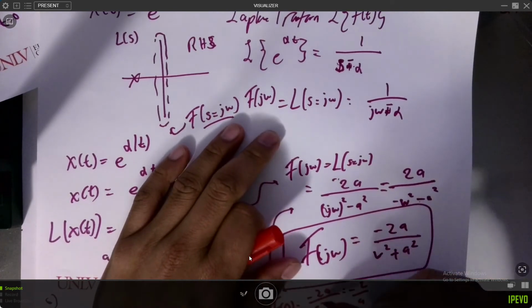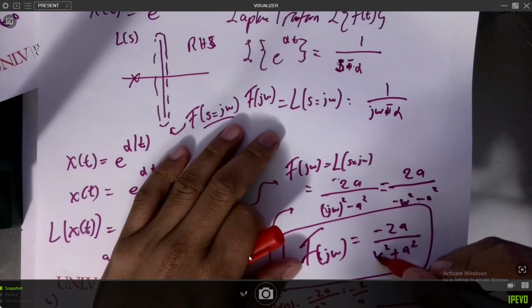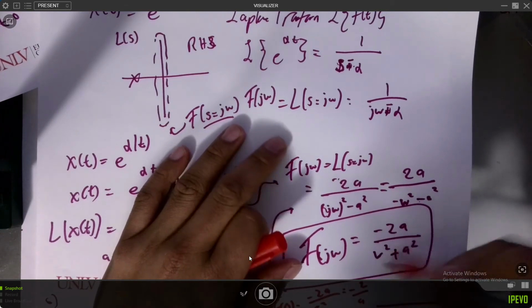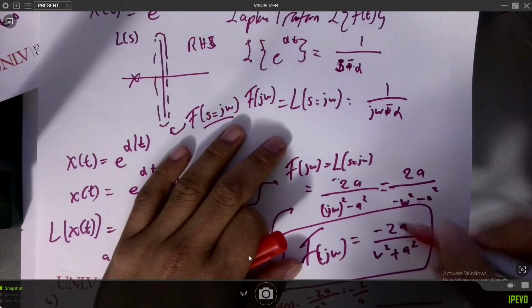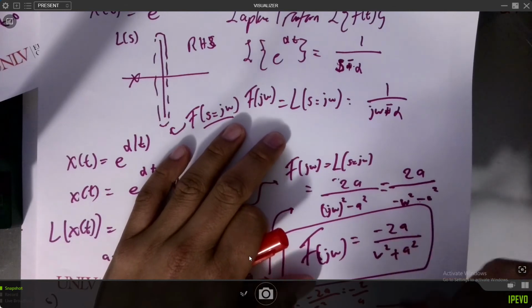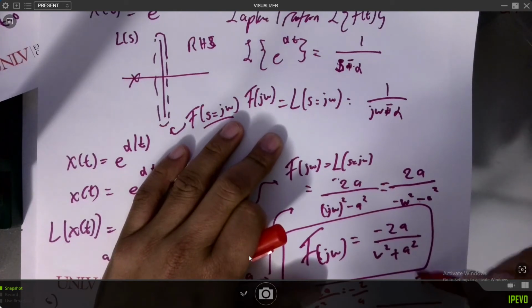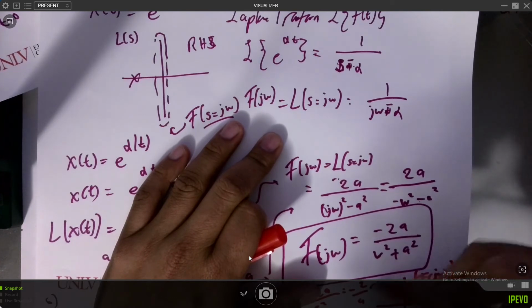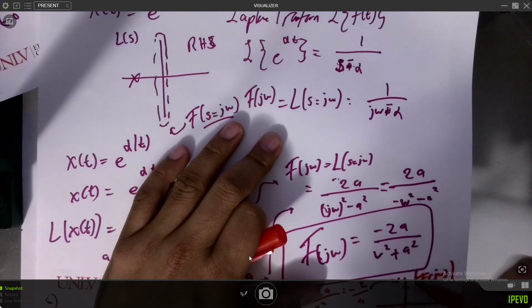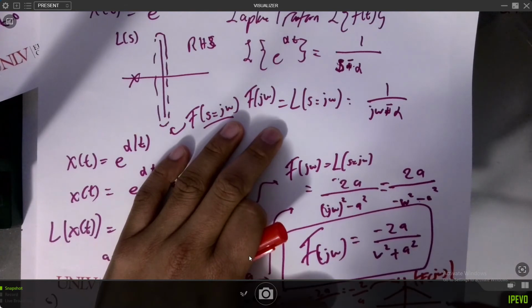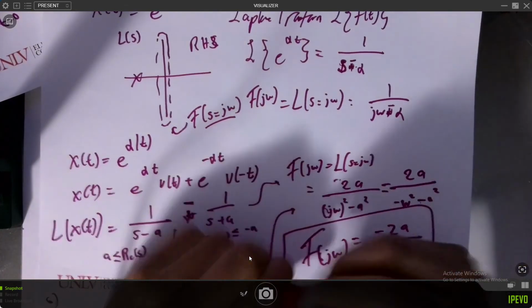And as omega gets bigger, the denominator gets bigger, and that means the entire number gets smaller. So this is the actual magnitude response of j omega. This is how you do your Bode plots too. You can do right here, which is that amplitude, and then it probably just goes down like this. You can draw a better one. This is the omega axis.